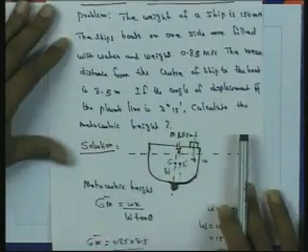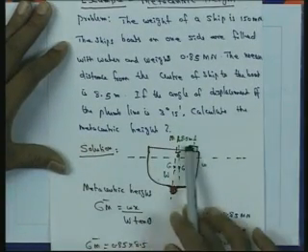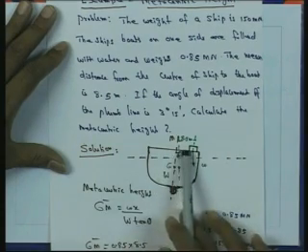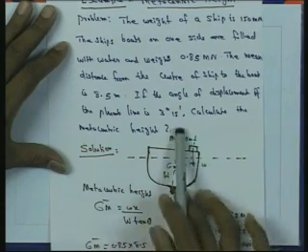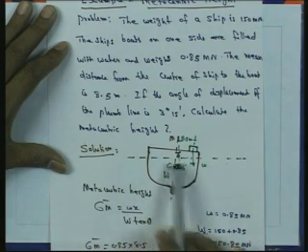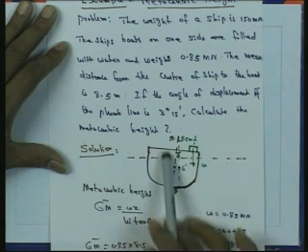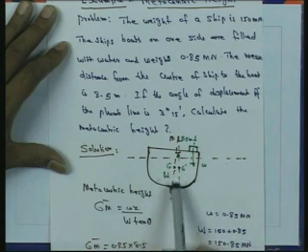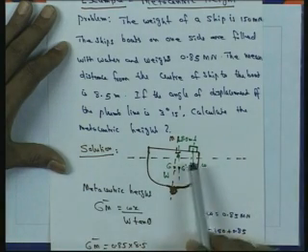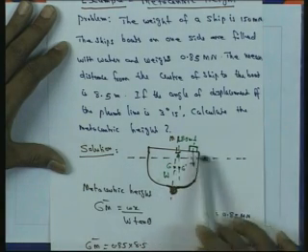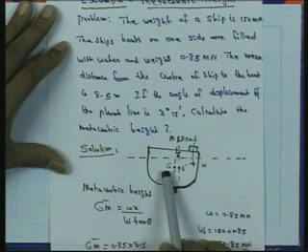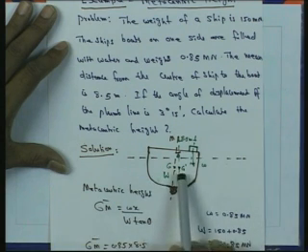So, in this problem the ship is given, and the small boat is placed at 8.5 meters. Initially you can see the central line is in stable equilibrium if the boat is not considered, and the center of gravity is here. The weight of the ship is W, which is given as 150. Since a small weight is added, G is shifting slightly to G dash.